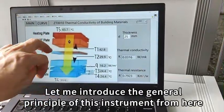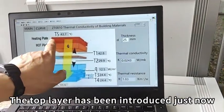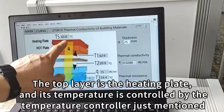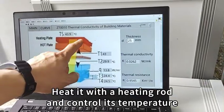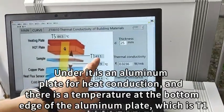Let me introduce the general principle of this instrument from here. The top layer has been introduced just now. The top layer is the heating plate, and its temperature is controlled by the temperature controller just mentioned. Heat it with a heating rod and control its temperature. Under it is an aluminum plate for heat conduction, and there is a temperature at the bottom edge of the aluminum plate, which is T1.